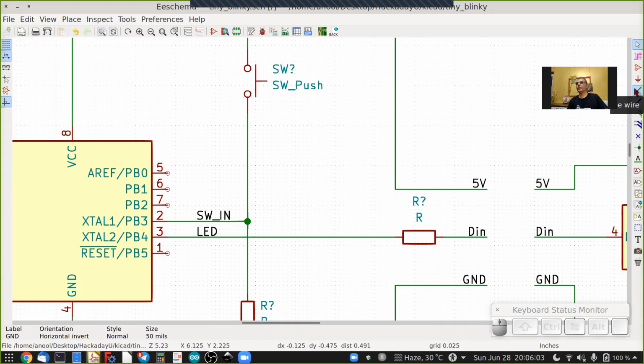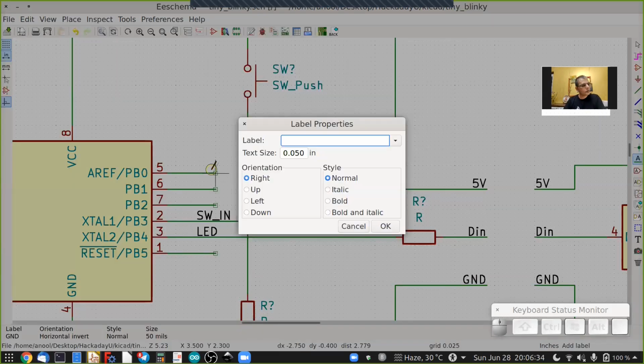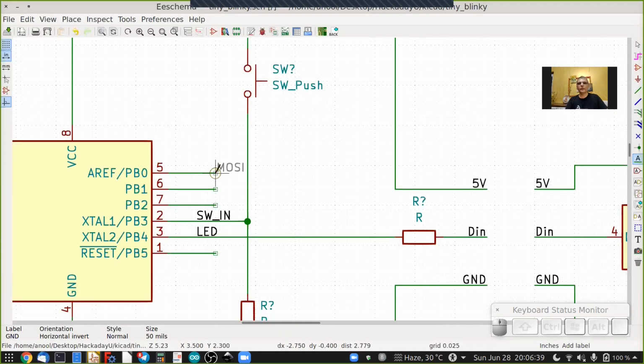So we're going to draw a couple of wires first. Like I said, this is purely for aesthetic reasons, but you can add a label directly to the pin as well. So I'm going to add 4 wires like so. And then I'm going to add net labels to these 4 wires. So use the place net label. Click over here once. And this one is MOSI. To point the other way around, press R twice. Click it here.